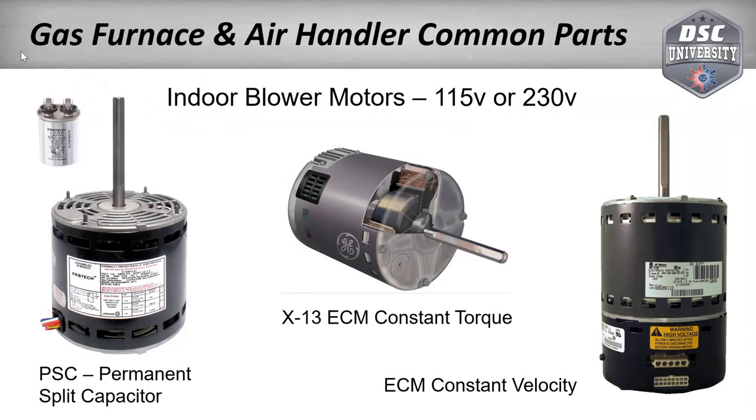So to start out with the blower motors, we have three different types of blower motors that we use in our equipment. Over on the left hand side you see the PSC, or permanent split capacitor motor. That's your standard motor. That's what we have used on your standard blower assemblies, your standard condenser fan motors. And the easiest way to recognize it is it has to have a capacitor with it to work. We'll talk more about the capacitor a little bit later. But that's your standard motor. That's your least efficient motor, your more economically priced motor.